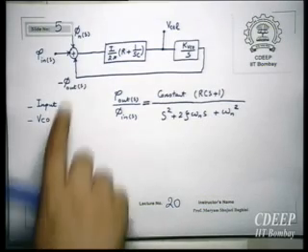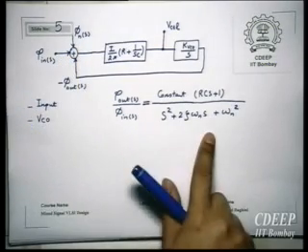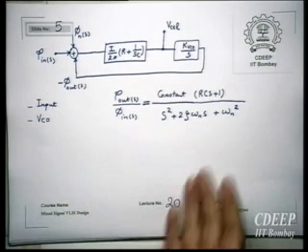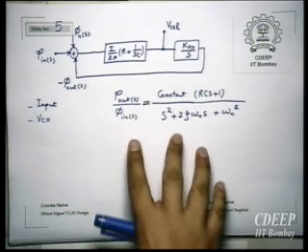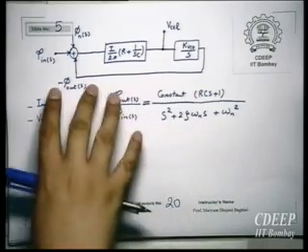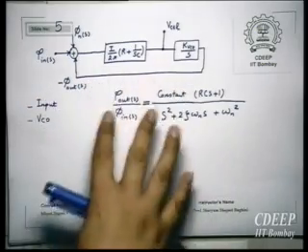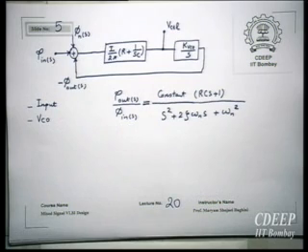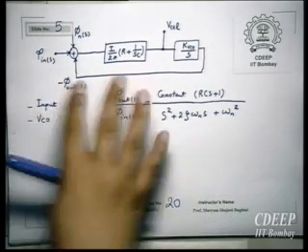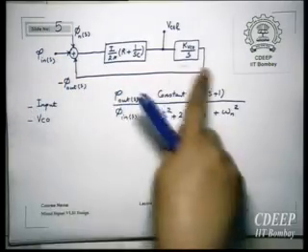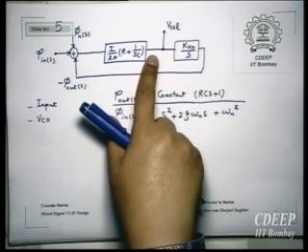So the transfer function for jitter at the input will be the same as the transfer function of the PLL loop, which is a low pass transfer function. Therefore, high frequency jitter automatically gets attenuated by the PLL. That is a good thing, because the PLL behaves like a filter for high frequency jitter. But for very low frequency jitter, this transfer function means it brings the jitter into the entire loop, because the low pass filter will pass it on.